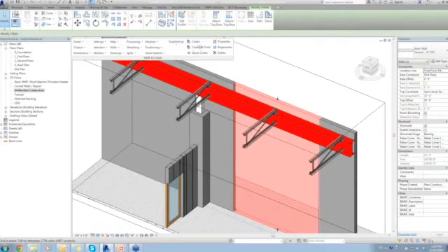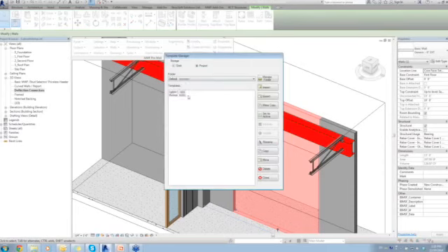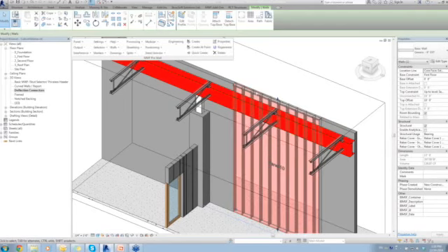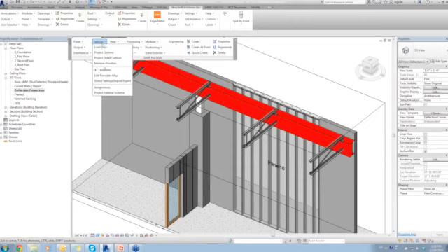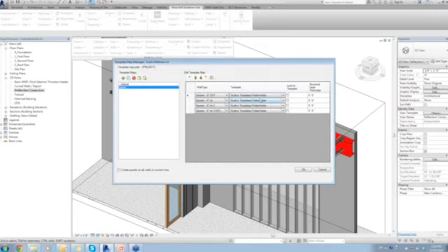I'm going to, again, place a template and use my exterior wall template I've created. Create. It's going to place that panel with that slotted track. I don't have to worry about performing any of the commands I've already shown. To expedite this process, we can also use MWF's template map option, which allows me to map my MWF templates to my Revit wall types.